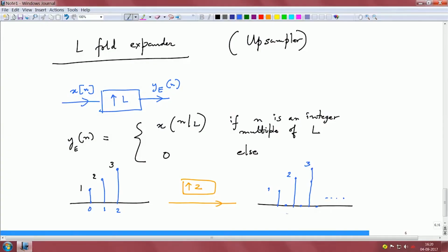Okay. Now, you may ask these questions as I am lecturing, I mean, there is no information that you are really conveying, right. You just have the same information here except that you have doubled and you have placed these zeros. But usually these operations of expansion or downsampling or upsampling, they have some filtering operations as well. So, once you upsample, you can imagine I need to have some interpolation filters to fill in these zeros, right.